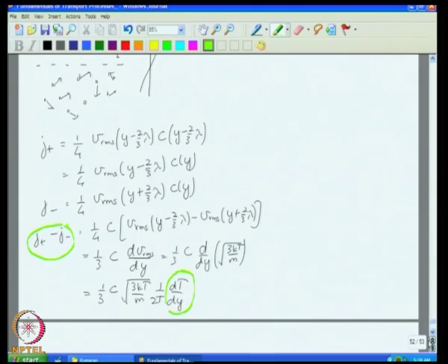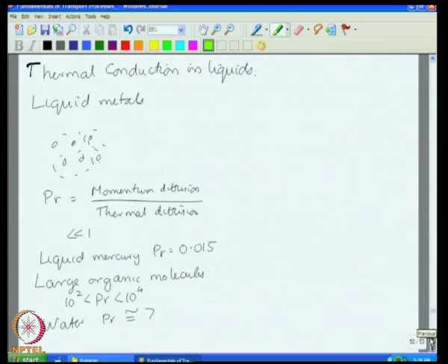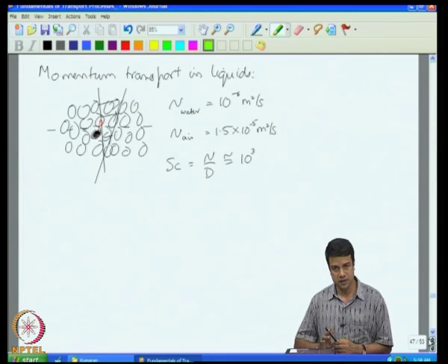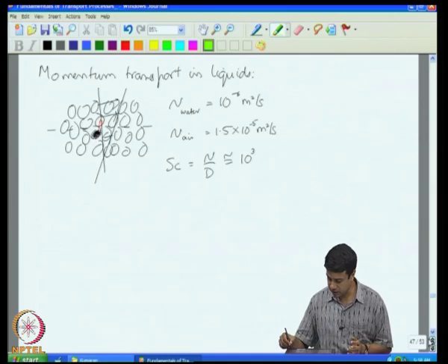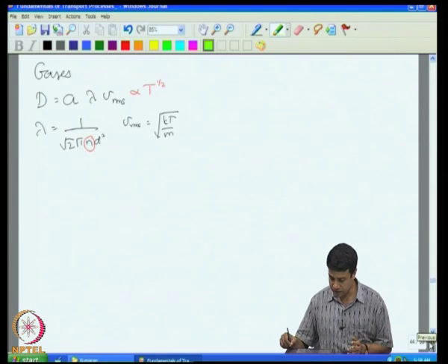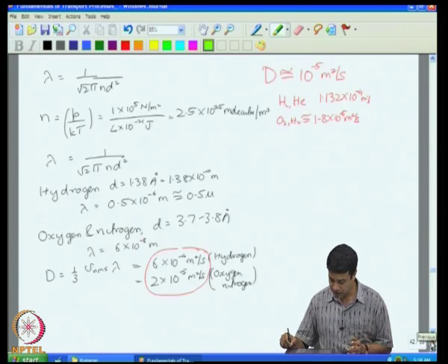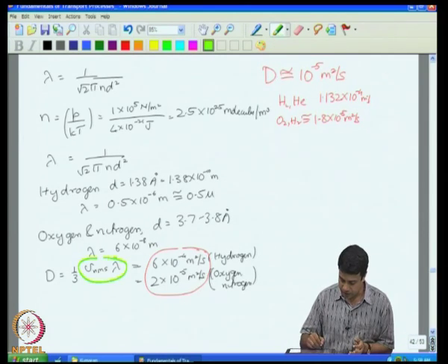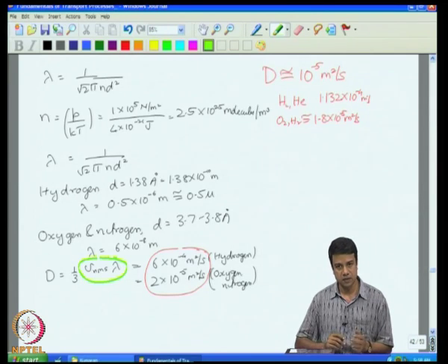So, for example, in these lectures on diffusion coefficients, in gases the diffusion process occurs by the same physical mechanism for mass, momentum and energy transport. Because of that, all diffusion coefficients end up being approximately given by the root mean square velocity times the mean free path in all three cases. I just told you that the Prandtl number is 2 by 3 and the Schmidt number is 5 by 6 for monatomic gases of hard particles.